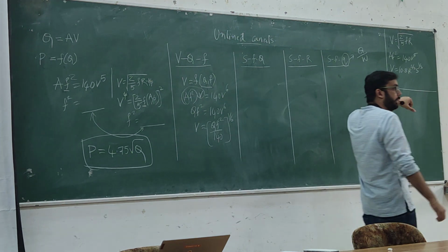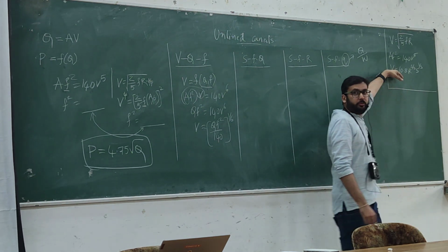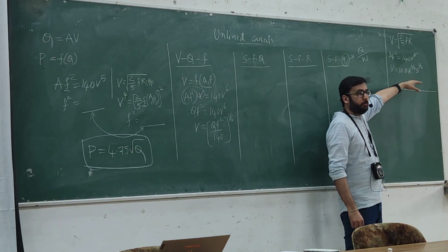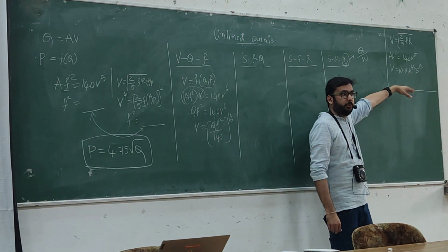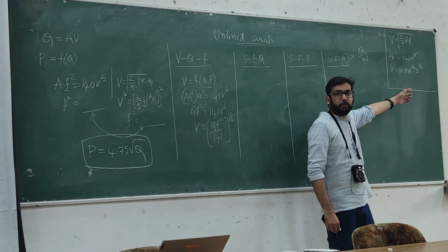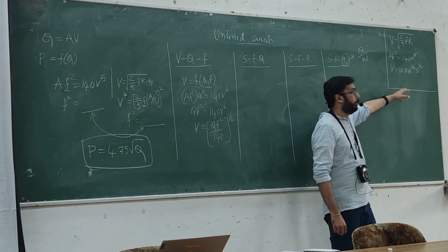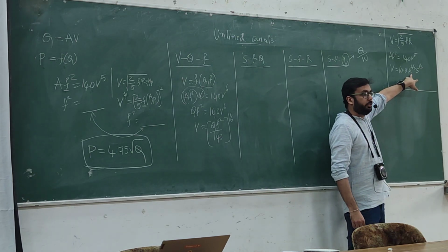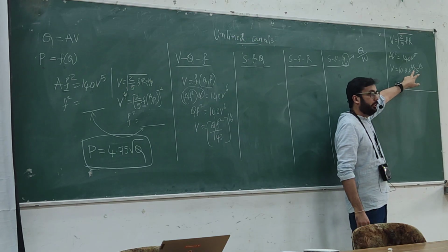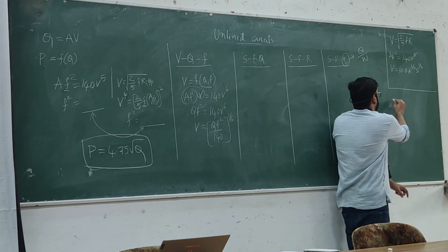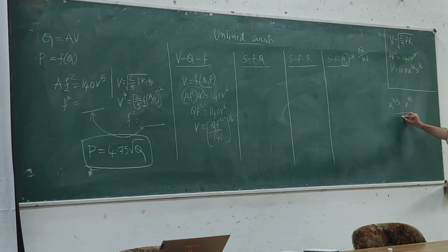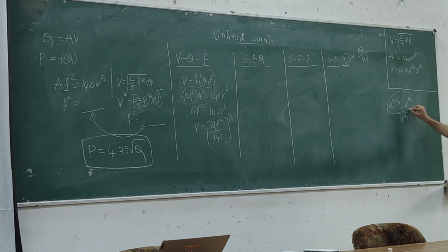How do we bring in discharge into this? So R is A by P. If you multiply by velocity and divide by velocity, then you would get discharge Q. Right, do you follow? So you have R. So within this R, you multiply with velocity P. So you have A power 2 by 3. So multiply with P power 2 by 3 and divide by P power 2 by 3. And this becomes your Q power 2 by 3.